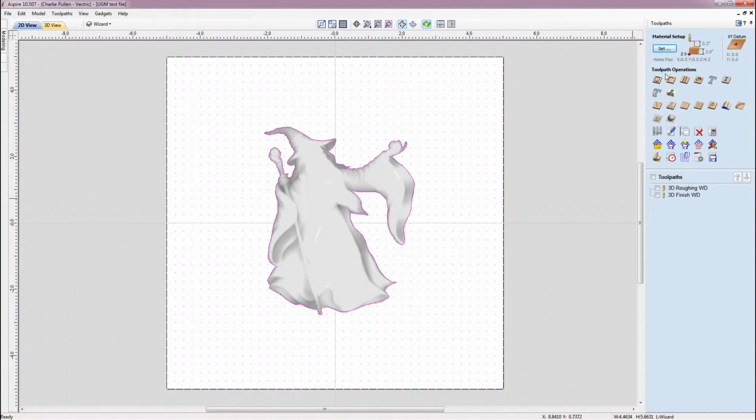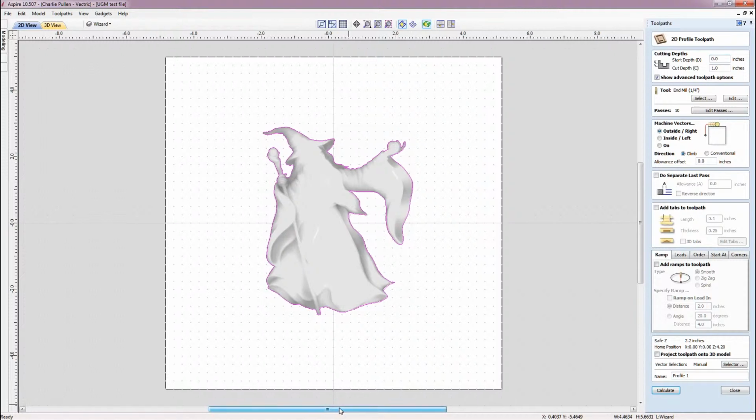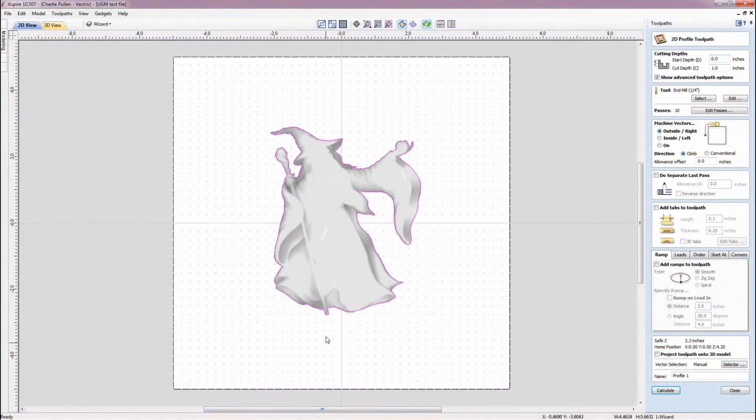And now what you can actually do is create a profile toolpath to run down the edge of your model and create a nice smooth finish around this model here for you as well. And that's one way you can get around some of the jaggedness that you may encounter with 3D modeling and some of the pixelation that we have down the edges of the sides here, because that comes up often in support tickets. Now it's important to note that again I have covered a lot of in-depth topics today in a very small amount of time.